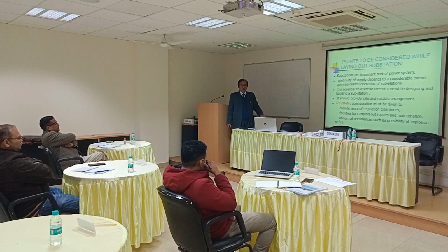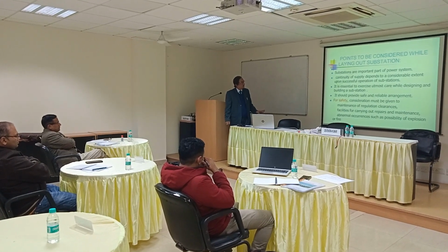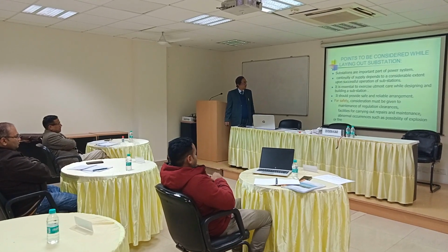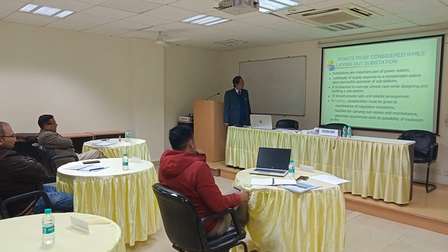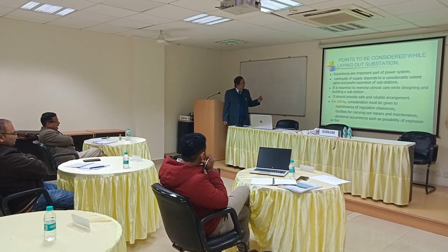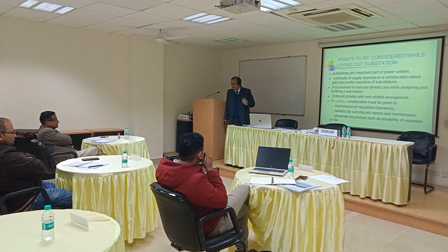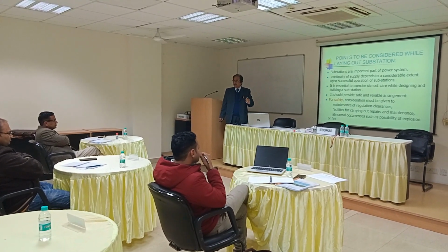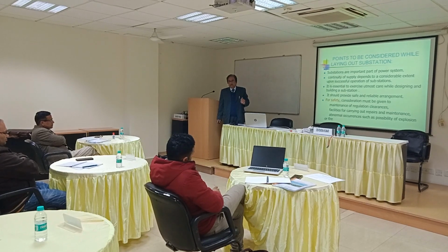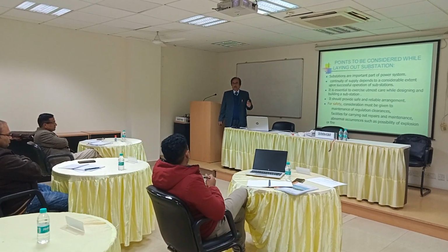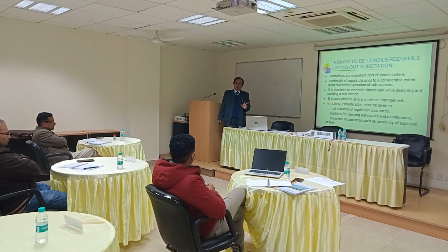Okay. Now, points to be considered while laying out the substation. Substations are an important part of the power system. Continuity of supply depends to a considerable extent upon successful operation of the substation. Basically, we have to design and install substation equipment in such a way that the substation is reliable and safe to work in.